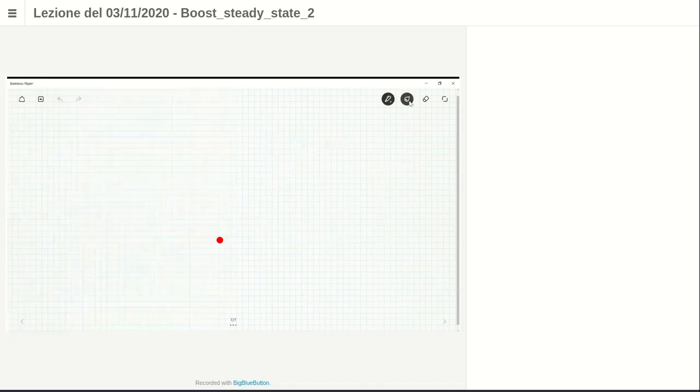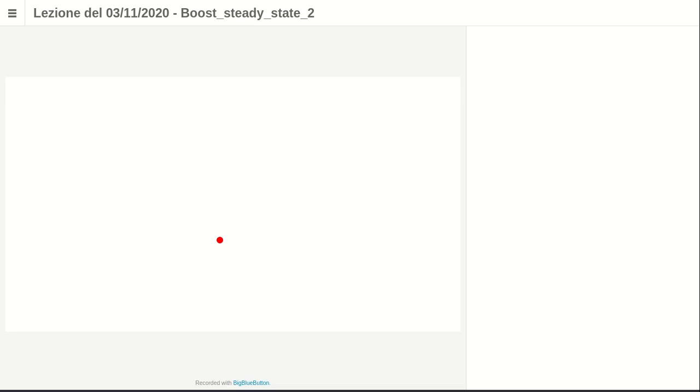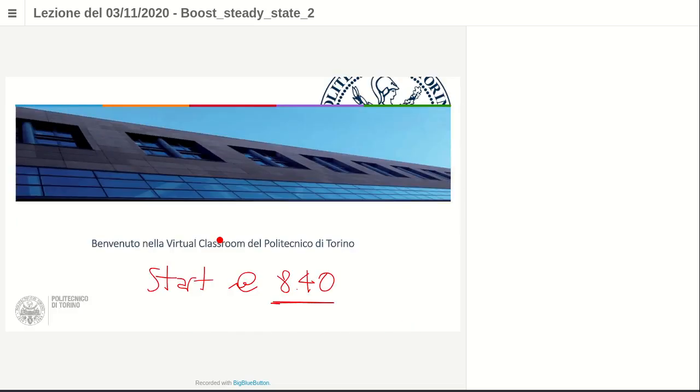Okay? So in this way, we have that the root mean square value is V naught over R (1 minus d), which is the input current, multiplied by the square root of d. Okay, this is approximated, but this approximation is a very good estimation of what happens. Okay, let me discuss a little bit this equation, this approximation.